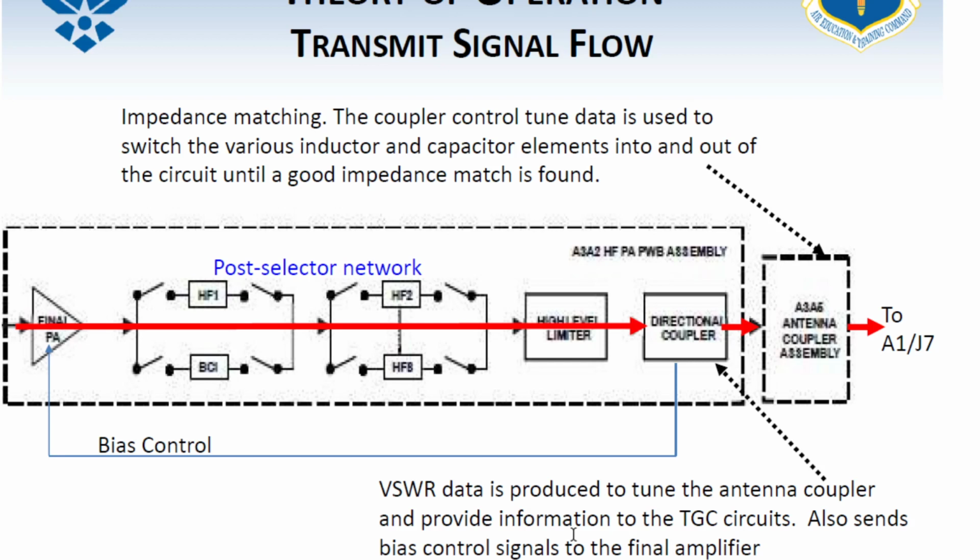So it's going to pass that VSWR data that it's collecting from the radio onto the antenna coupler so the antenna coupler knows how much impedance is coming through and how to match that impedance as it comes through, so it actually gets through the radio and transmits. We do not want an impedance mismatch because that would cause voltage to come back through the radio and cause a bad VSWR ratio. Basically a 3-to-1 is a bad VSWR ratio. That's not something we want.